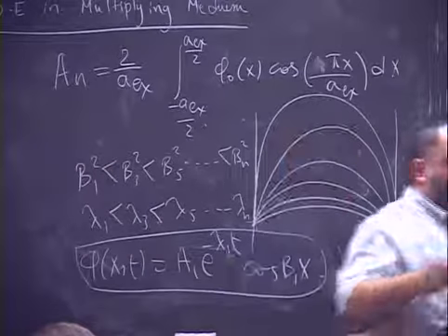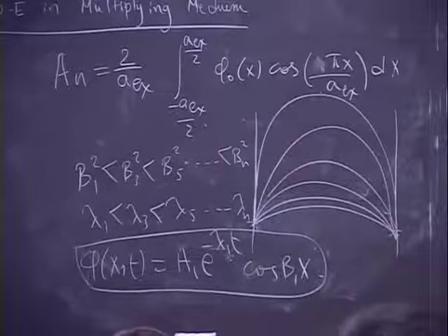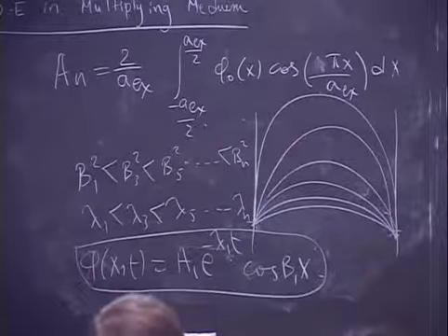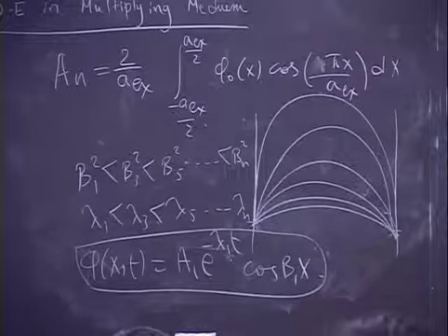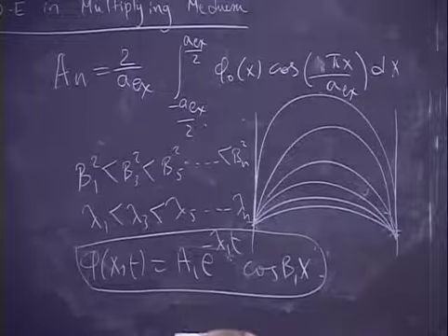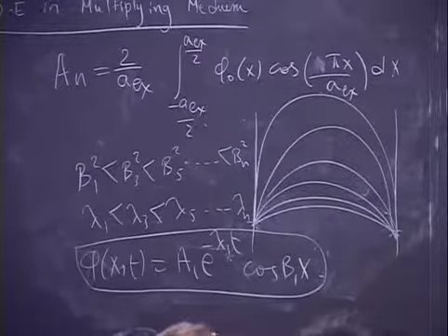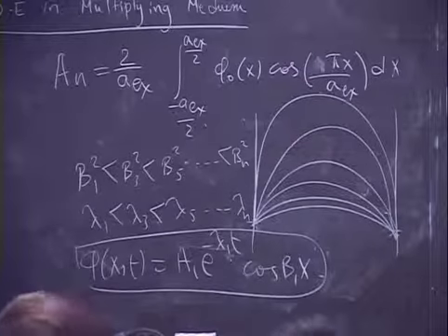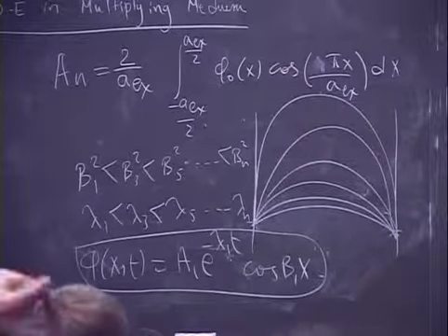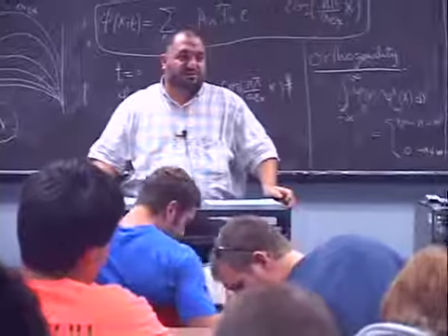Next time we'll continue. Do you have any question? Yes. So you're saying at startup, we might see these higher order harmonic curves. Yes. Not startup, at transition, if the flux is constant. So when a transient is significant, then that's when we see the higher order. Let's say when you have a transition from a steady state, you will start to see those harmonics, but they will die away very fast. Right. And you will end up with the first harmonic, which is the flux.